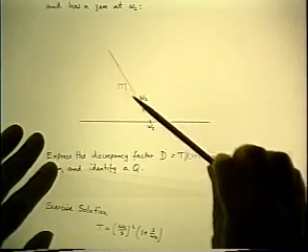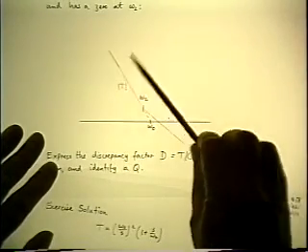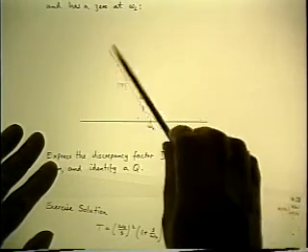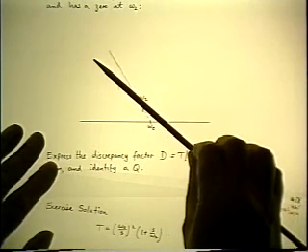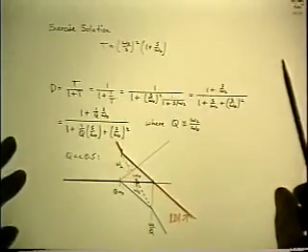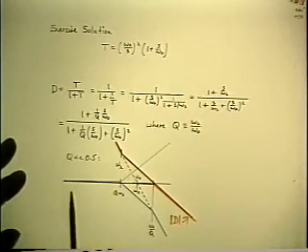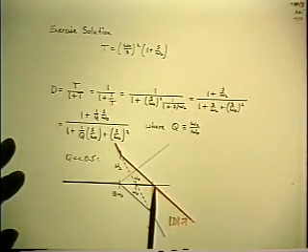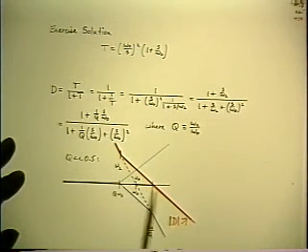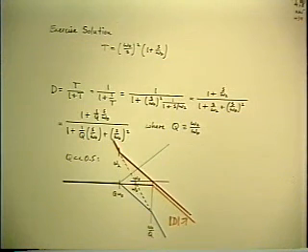that is, as long as the omega 2 is low enough down here, the double slope part of it isn't doing anything. And you're back to essentially just crossing over on the single slope, which is the ideal reference case. And that's what has happened in this case here, where Q is low enough, the closed loop discrepancy factor simply stays flat and has a single pole, which is the most graceful way it can roll off. So that's the base case.